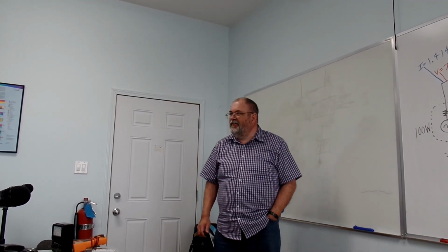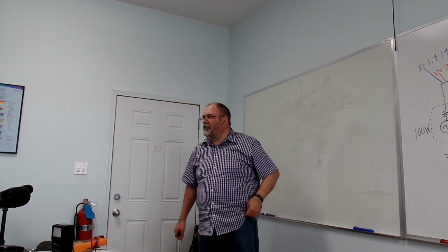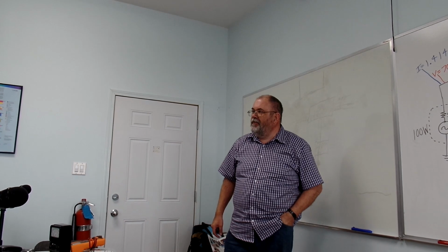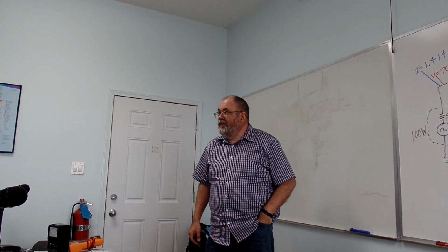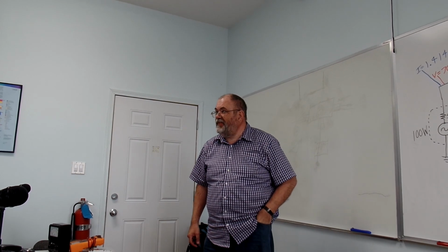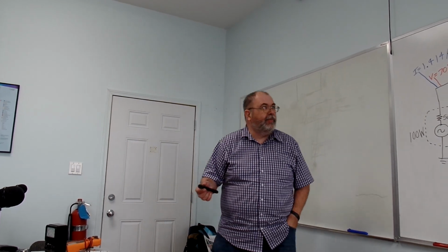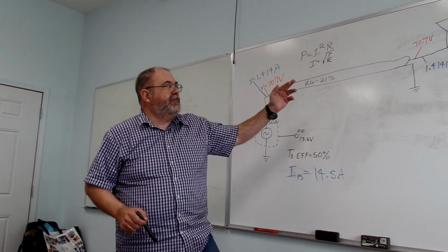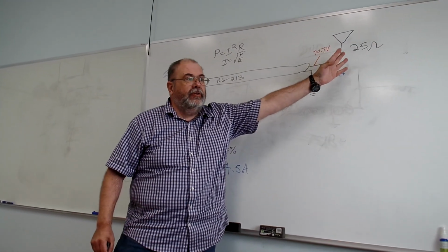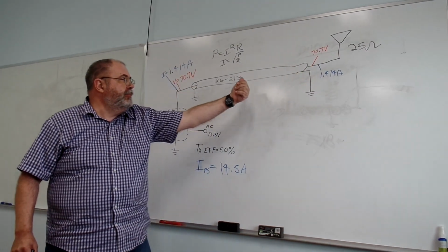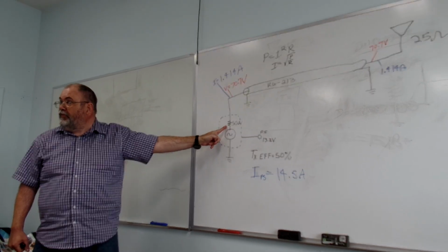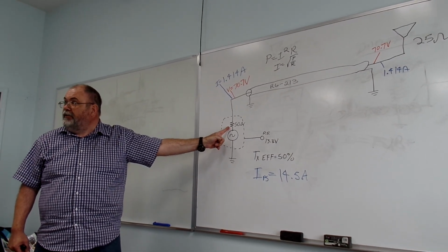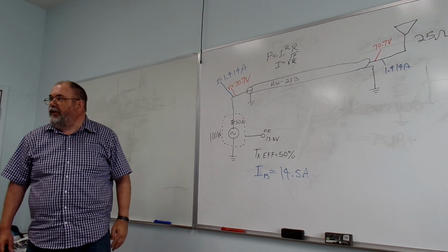Heat? No, everything's lossless. There is no heat loss. Well, it's getting reflected back. So 50 watts of our power is still going into the load, 50 watts comes back the other way, and when it sees this 50 ohm resistor, that will dissipate it as heat, and we'll be happy.